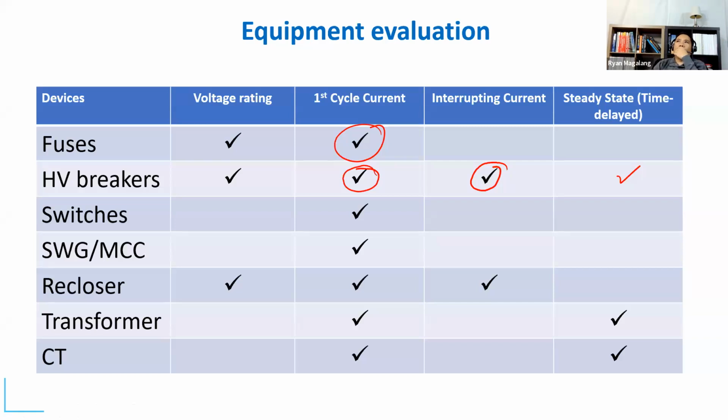When it comes to relaying, well, fuses are also part of relaying. By the way, I'm referring to the time current coordination. When it comes to that, depending on your coordination interval, as I mentioned earlier, you may have to look at the first cycle and steady state.